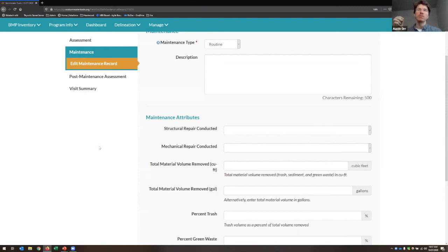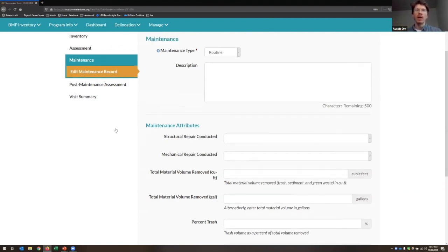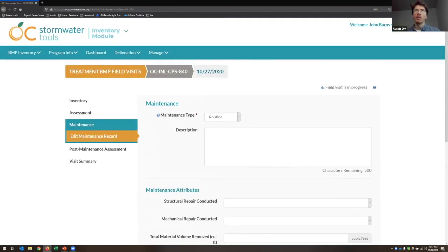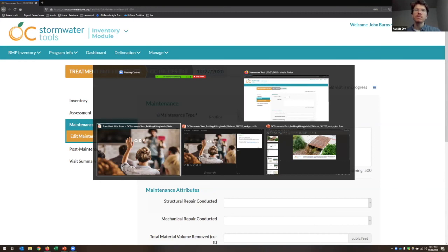And then we perform that calculation using that percentage of capture based on the nomograph calculation. But yes, the volume-based BMPs' long-term performance is calculated based on long-term routed hydrology, based on local rainfall gauges.